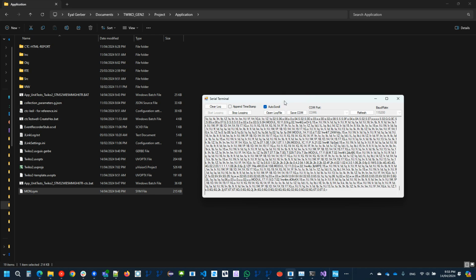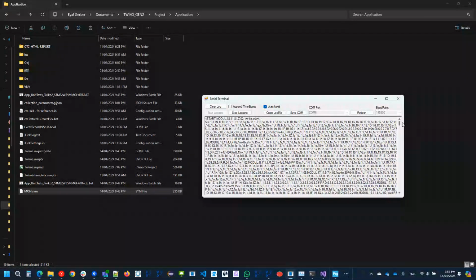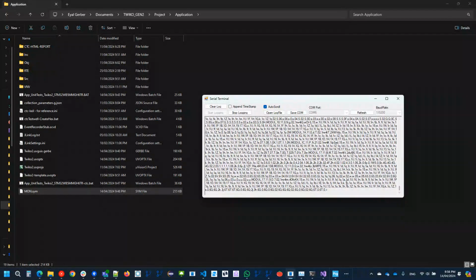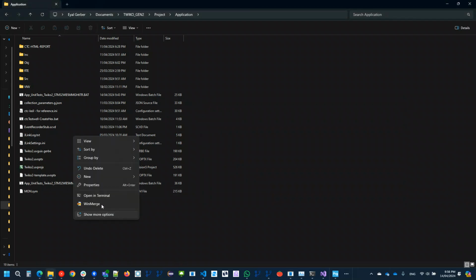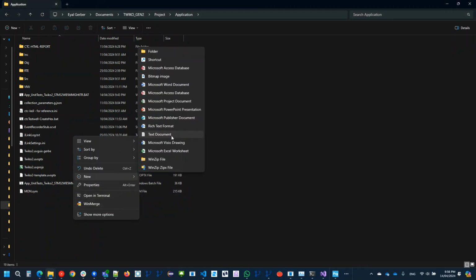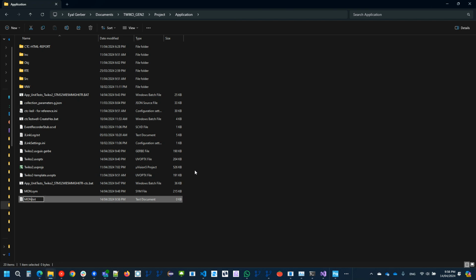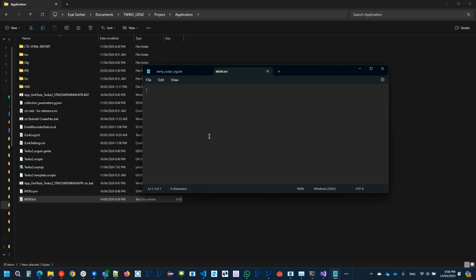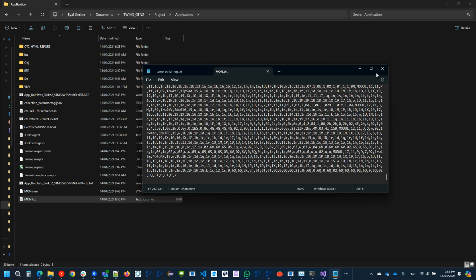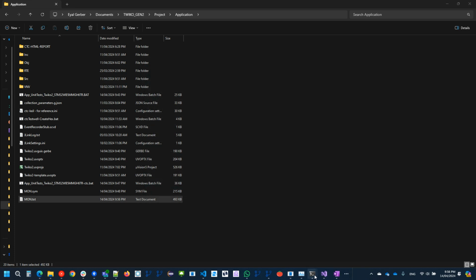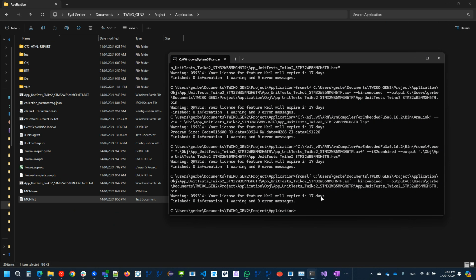All right. So now all the serial data has been received. Okay, all of this, which looks like gibberish, I know, is the coverage information. I'm just going to copy all this, and right here I'm going to create another file. Call it mon.txt, and paste all the information here. Save. Okay. Go back to CMD. Now I'm going to run the following command: ctc2dat.